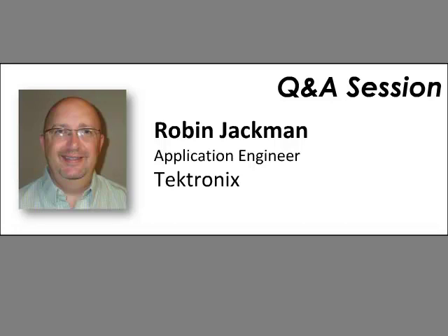Someone is saying, I need to do EMI diagnostics on an engine. Do you have any advice related to EMI from an engine, or do you only know about PCB EMI? Well, that's a very good question. The EMI standards for engines are, of course, a little bit different than EMI standards for other products. We don't really have conducted measurements per se on an engine because the engine is not connected to the AC mains. Curiously enough, low-frequency EMI is usually of importance to most engine manufacturers because there are a lot of low-frequency clocks in the engine control units themselves.